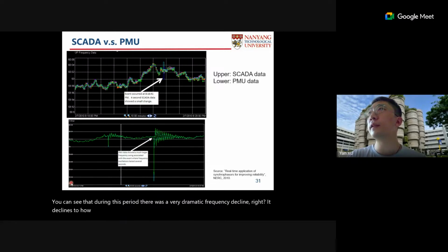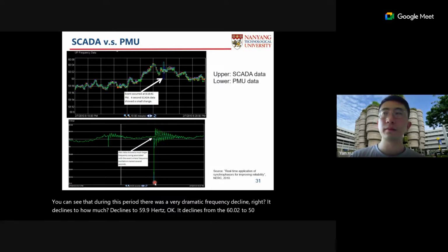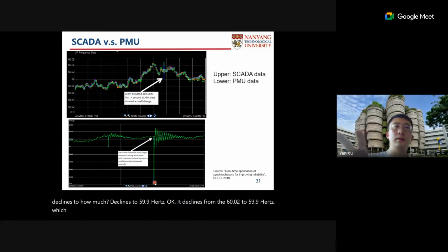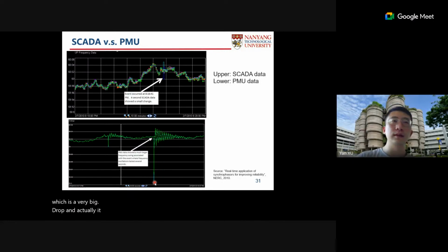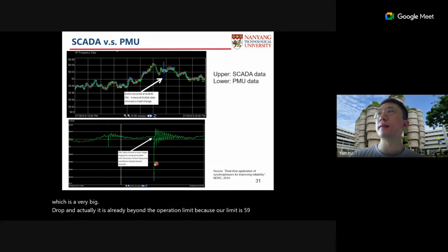It declines from 60.02 to 59.9 hertz, which is a very big drop. And actually, it is already beyond the operation limit because our limit is 59.96 here.